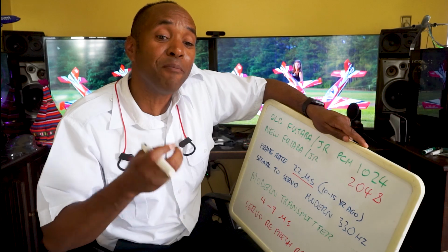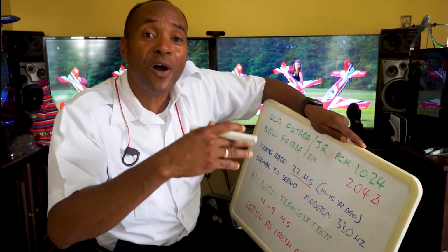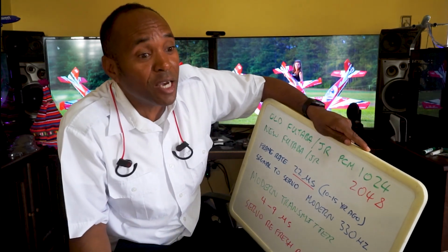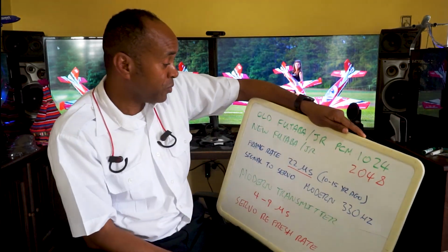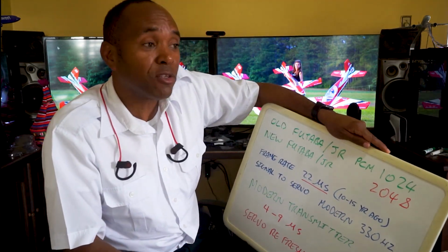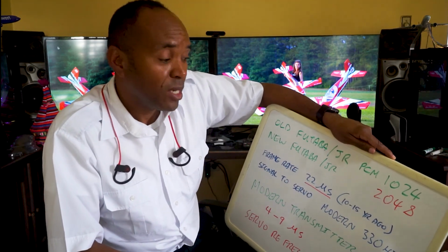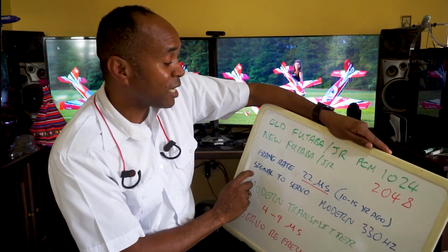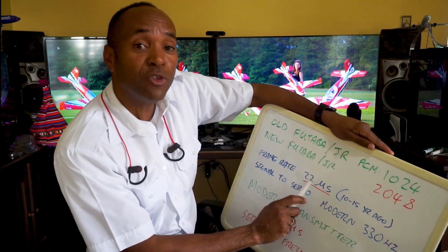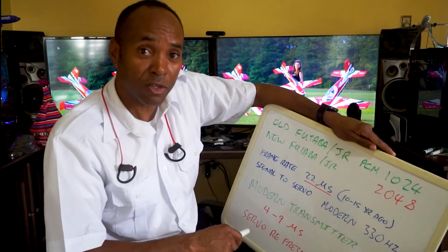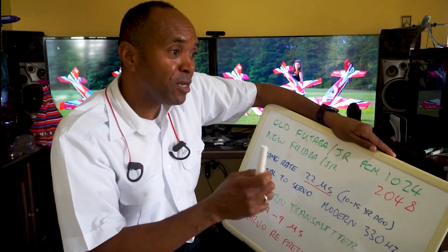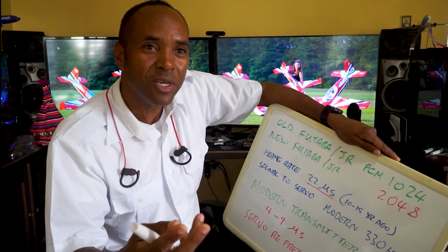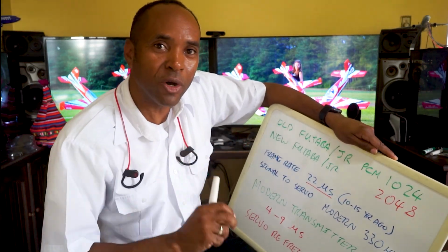Now when you go and take your money and buy a servo like this, you find it far exceeds the capability of your old equipment. It may work as well as it may not, we're not even sure. So what we have now, my old GR12X that I bought 14 years ago, has 2048 resolution, which I explained already. It has a frame rate or a latency of 22 microseconds. That means every 22 microseconds you get a refresh of the signal that's going out.